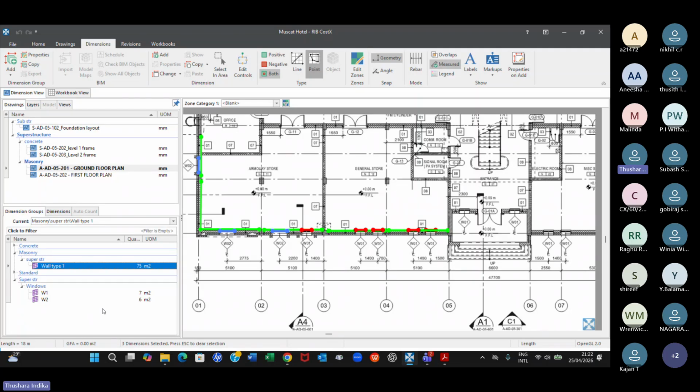But can you practice that? I'll give you 2 minutes. Now, since you have measured W1, W2, I want you to copy this W1 into wall type 1 and W2 into wall type 1 and then make negative dimensions, and then I want you to change the height as well, because when you copy W1 into wall type 1, W1 dimensions will get the height of wall type 1.